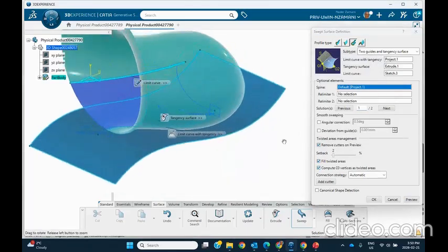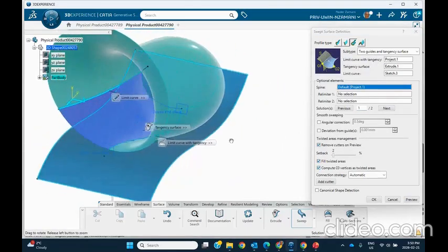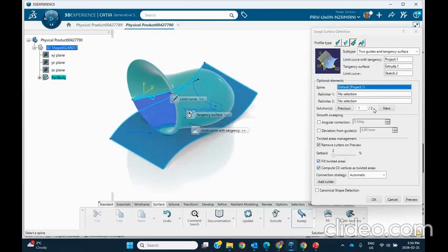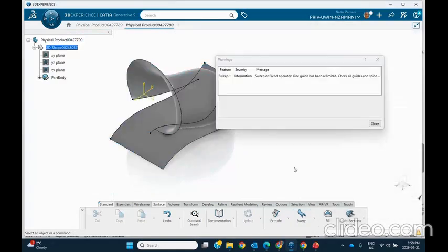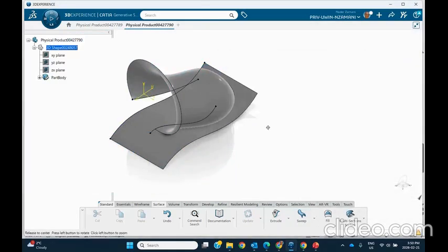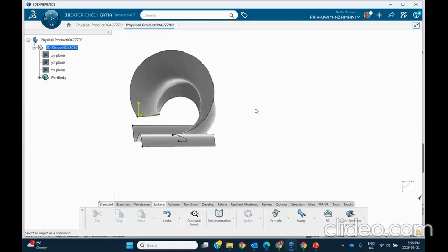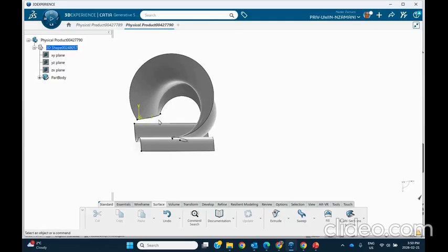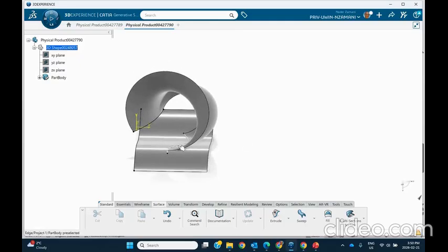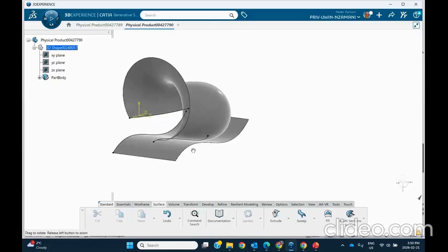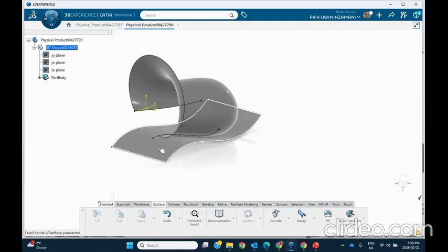Okay. So let's see if this all makes sense. Well, first of all, there are several solutions. There's two solutions in this case. And let's say, okay, this is the first one. So here's the situation. Let's see if it meets our requirement. It went through the curve that's off the surface right there. You can see that. See that? Off the surface. And it goes through the curve that's on the surface. And the resulting surface is tangent to the original extruded surface.